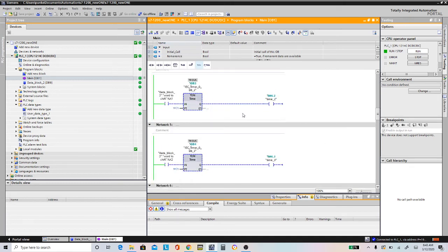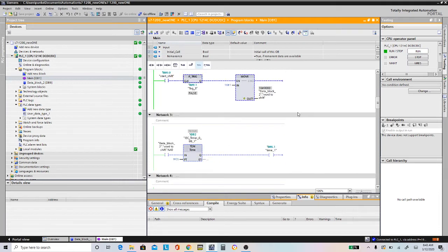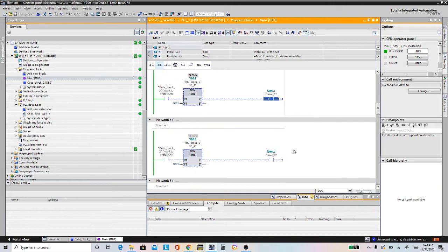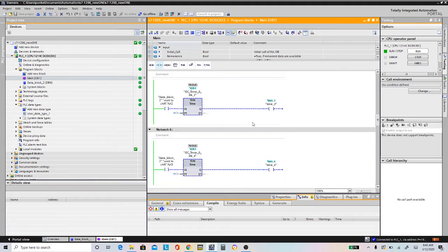What's good about this shift left is there's a lot you can use after it. Let's say after bit 0 is on, I can make this do something. Then when that's done, bit 1 comes on, and I make that do something. That's really how automation works. You have sequential order.